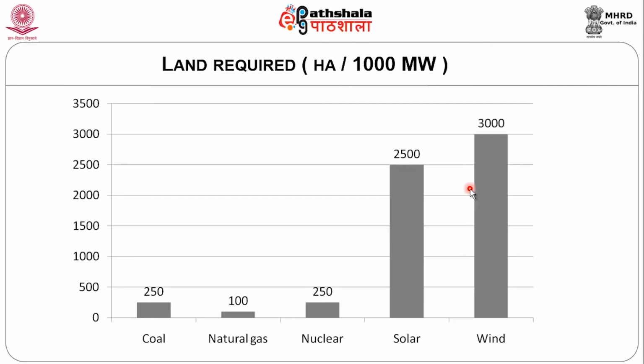So in this lecture, we have seen so far the land requirement and the Betz limit. Importantly, we have seen how much energy could be tapped, and the derivation from Bernoulli's equation: what is happening upstream, what is happening downstream, what is happening at the rotor, and we are equating and arriving at the Betz limit, which is about 59.3%.